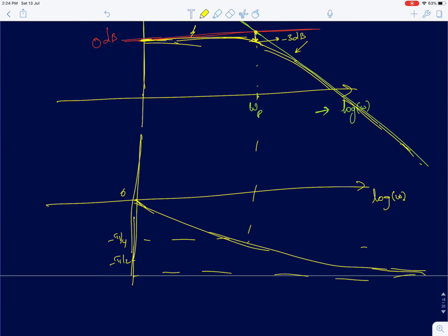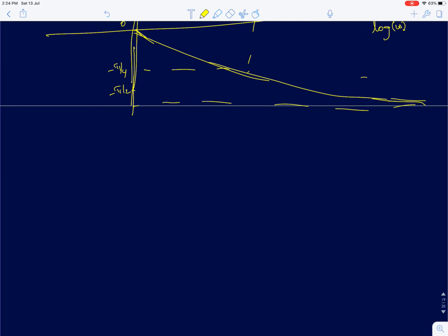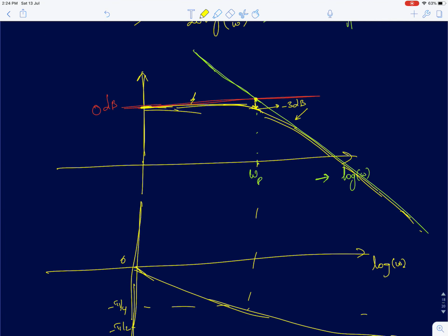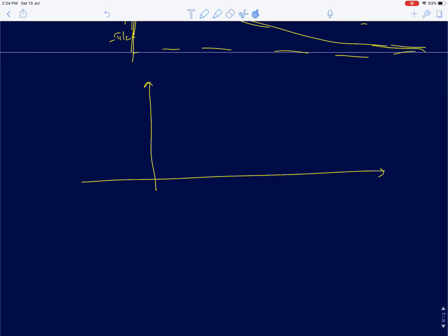Now, normally for engineering applications, when you are showing it as a graph, we just show it like this. We just show it using straight lines. If you look at the actual Bode plots, they are shown as straight lines. If you look at it asymptotically, this is a straight line and the green line is a straight line. But the actual Bode plot has some curvature here. When we do some hand design of systems, or when we're analyzing systems, we don't show that, it's assumed. So we just show it directly like 0 decibels